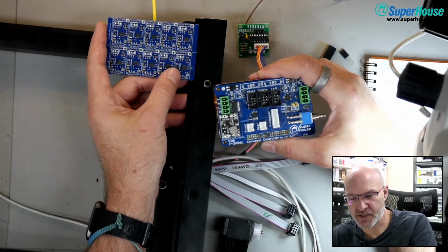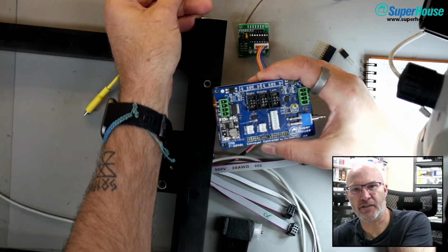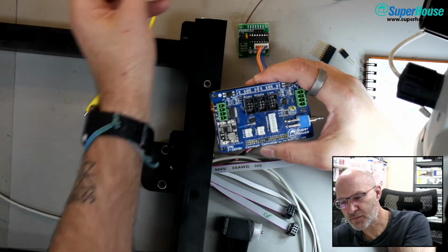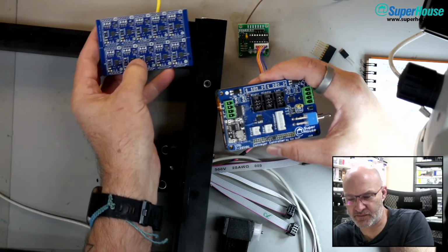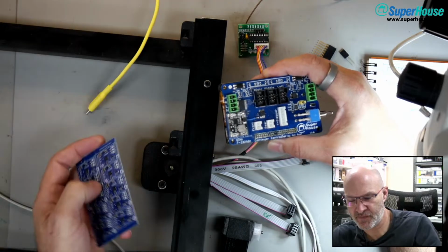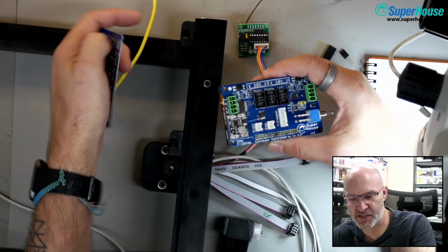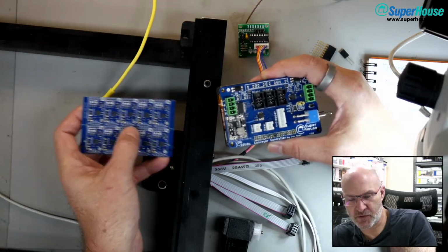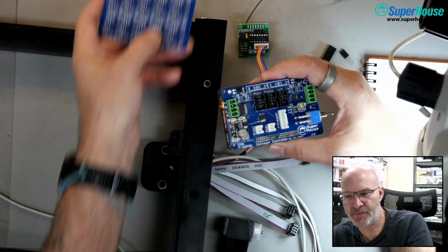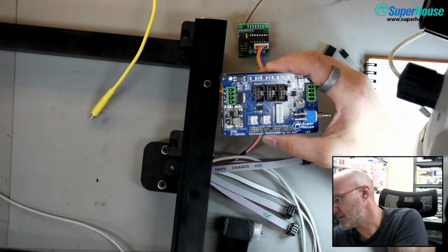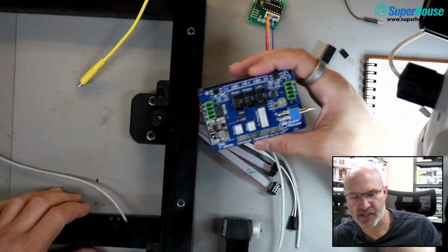After that, it will turn itself back on and it will move the board off, and it will go onto the conveyor of the reflow oven. And it'll know when the board is cleared, because the sensor will tell it that the board has cleared the conveyor. And what it could do is then run until the next board comes up and brings it to the exit point. So there could be several boards in the queue here, and it can feed them on one at a time at a predetermined rate. And I can do that without needing any of the ready in, ready out sensors, because it's just time based.